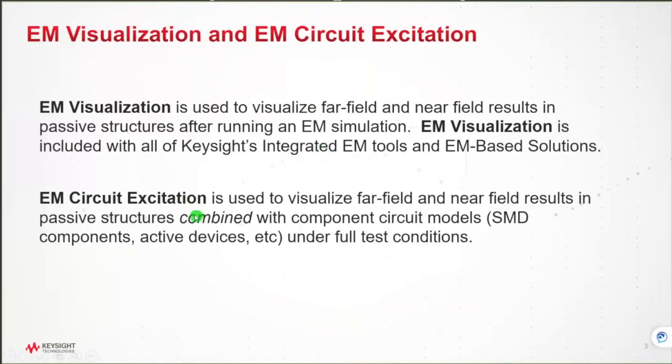EM circuit excitation is a little bit different. It allows you to do the same type of visualization of the near and far field of the structure, but it also combines the component circuit models, which are typically your SMD devices, active devices, things like that that were not part of the EM simulation.